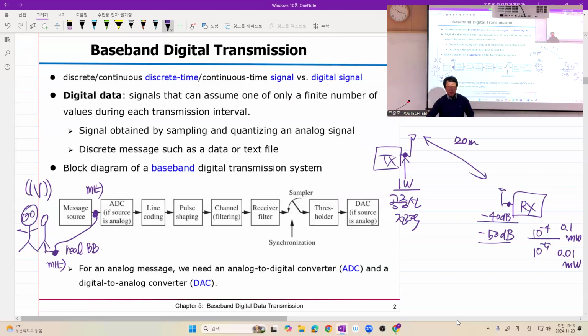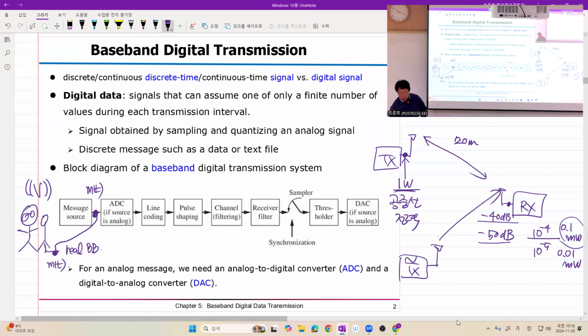So it's like your Wi-Fi transmitter is just around there. Your received signal power is around negative 10 dBm, which means that you have 0.1 milliwatt, something like that. Of course, your Wi-Fi transmitter does not transmit at 1 watt, but that's what I want to say. This is one, and the other is that in wireless communications, there may be interference in the same frequency band.